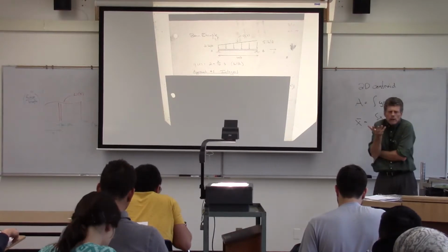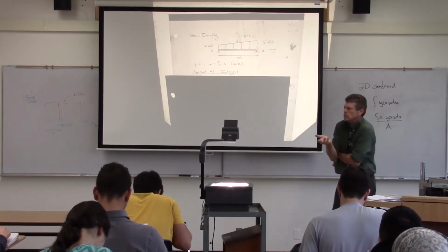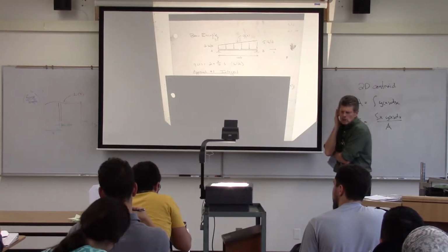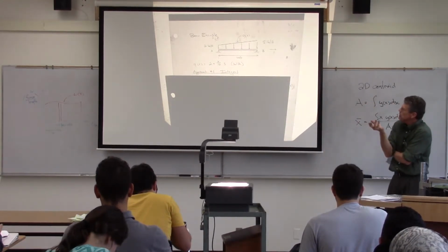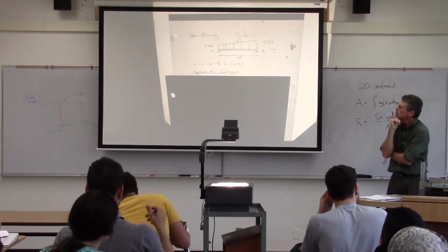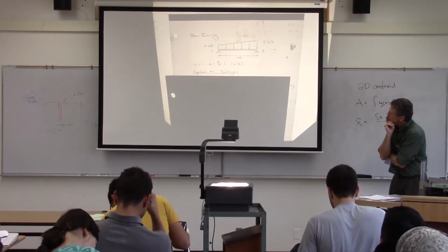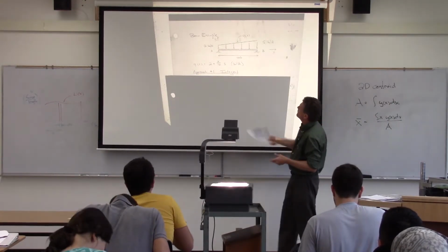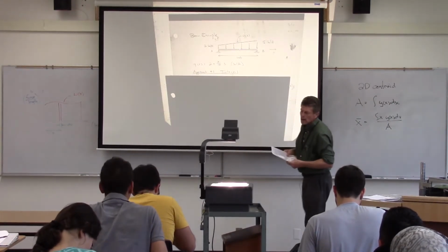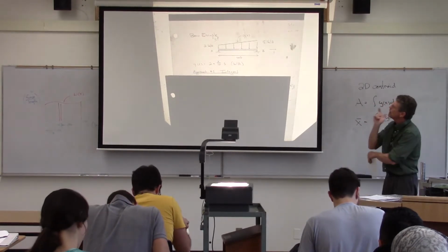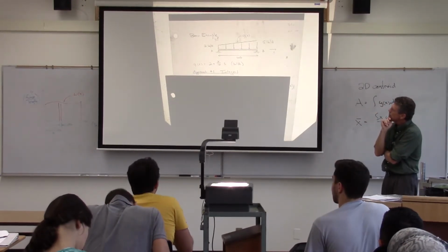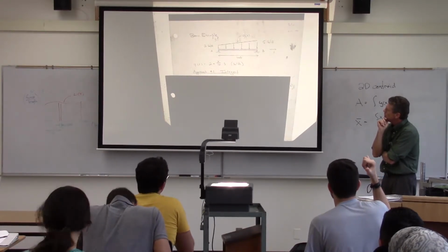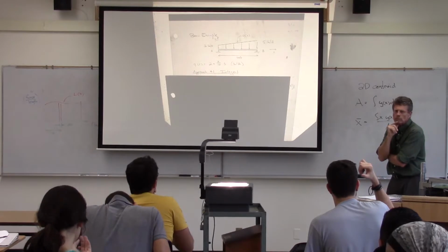And again, what we're going to be interested in is finding out what those support forces are. What sort of reactions am I going to see at A and B? In order to do that, the first thing I need to do is create an equivalent load from that distributed load. Now, note, I can express the change in load intensity by a linear function. So it'll be 2 plus 3 over 10 times x.